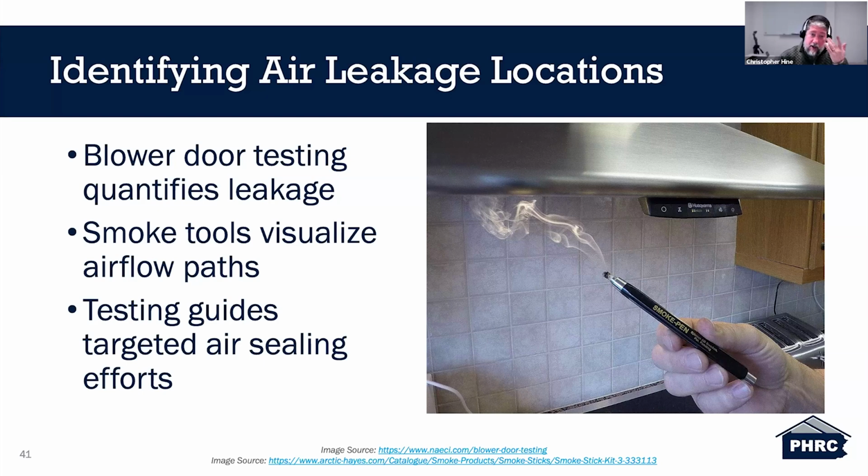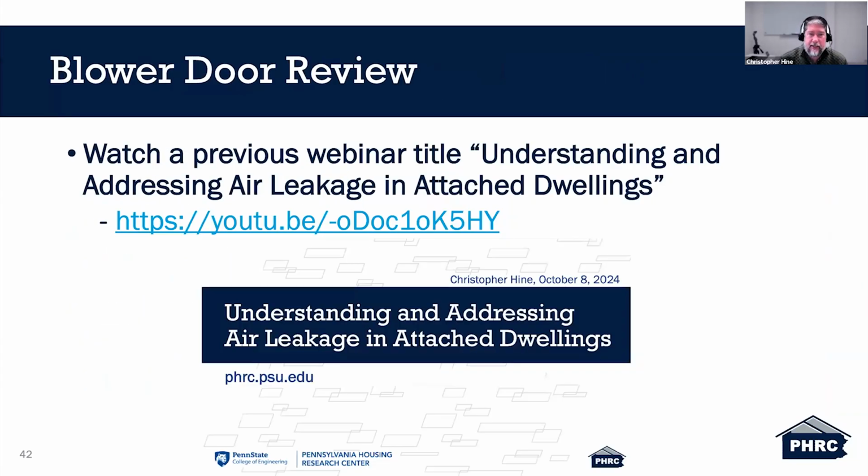So testing guides targeted air sealing efforts, right? So you're not just blanketly going through and guessing where your air is leaking. You can do it through testing.